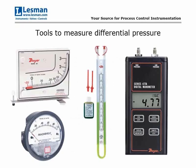The good thing about the slack tube manometer in the middle and the incline manometer on the left side is that they're using a fluid inside of there. And the fluid is great because it essentially will zero itself, or it's very easy to zero those manometers, versus a digital manometer. It does have a zero on it as well, so you can zero that and you can change the zero set point. But as far as a calibration standpoint, you'll want to make sure that if you are using a digital manometer that it is calibrated. A slack tube or an incline manometer requires little calibration except for maybe adding some additional fluid inside of the manometer itself if you lose some.